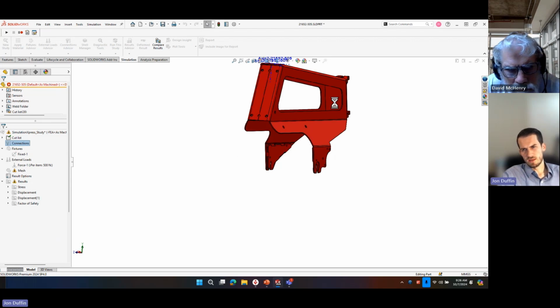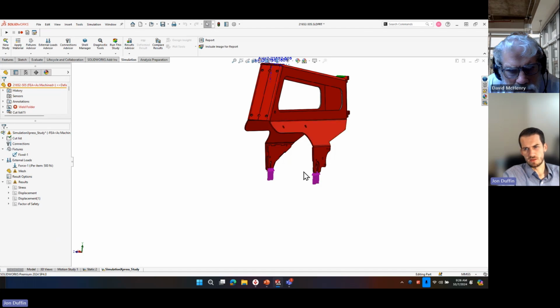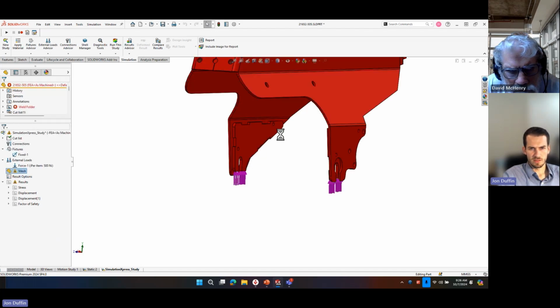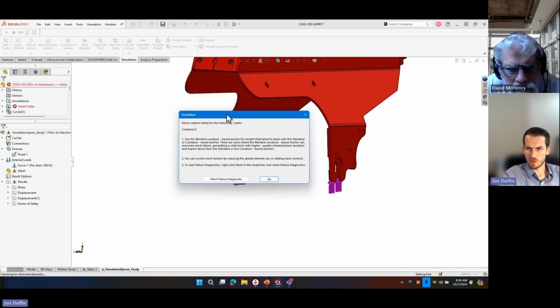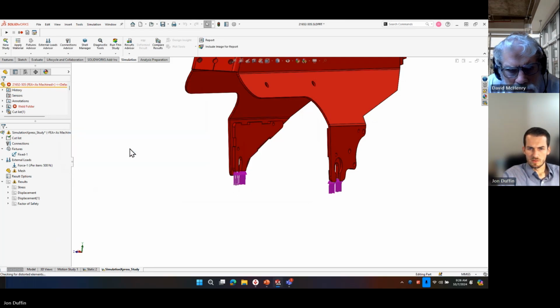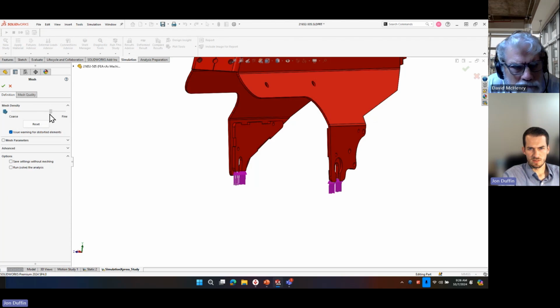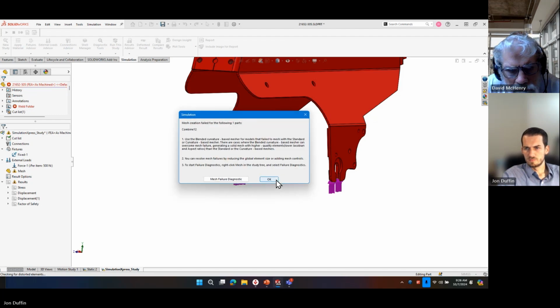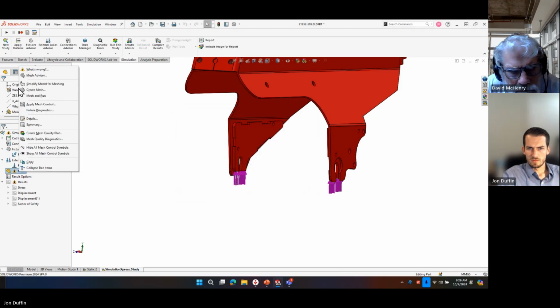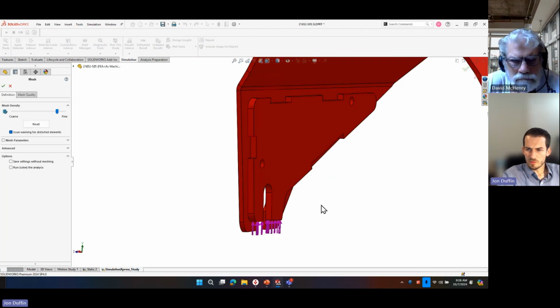But for the most part, it seems like when it got thinner, that's when it failed to mesh. We'll take a look and see if we can find out in this case. Okay, yep, it failed on this one, somewhere on this. So I'm going to try to reduce my mesh size, or make it more dense. Okay, somewhere in there it's getting too thin.